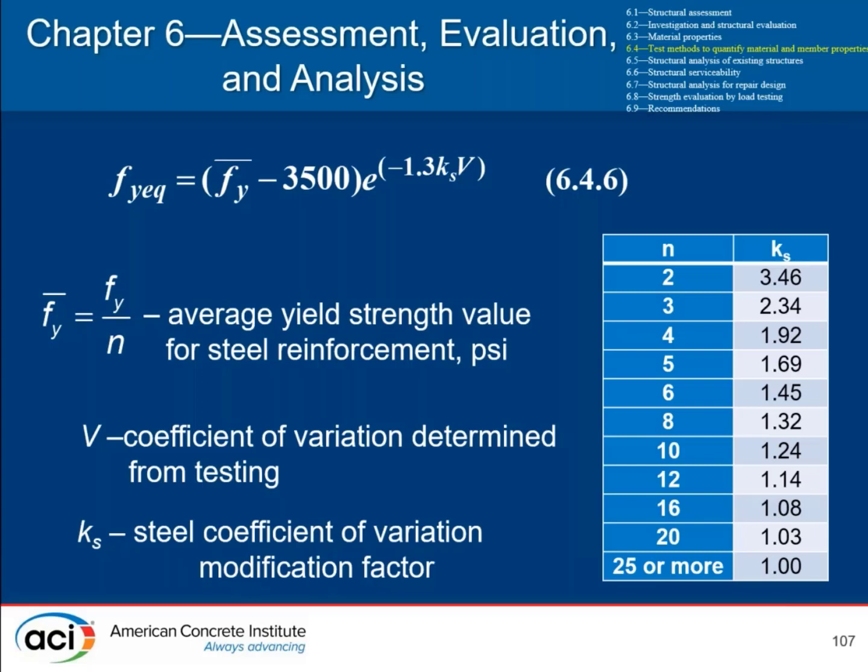I guess the thing I might observe is that typically steel reinforcing bars, if they're the same size in a structure, they've probably come from the same heat of steel. So the mean yield strength may not be a whole lot higher than is assumed in the calibration for new construction. But because they're all from one heat, the coefficient of variation is often much, much smaller than it is for sort of design where steel bars from all heats have to be considered.